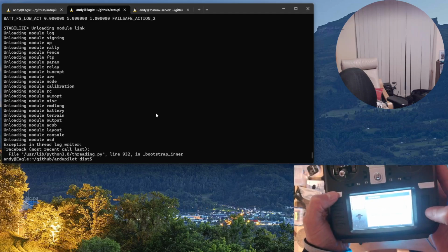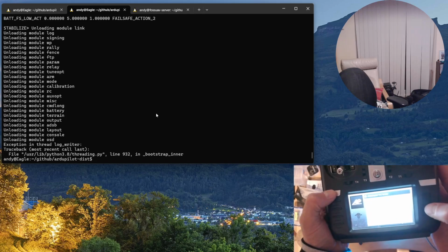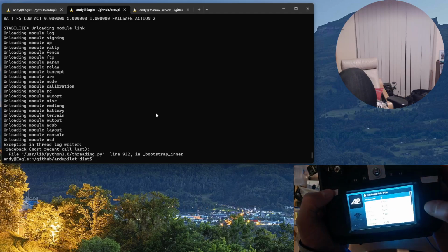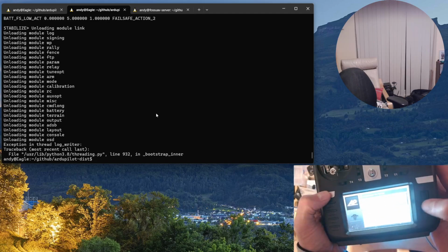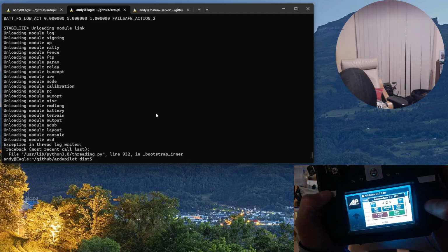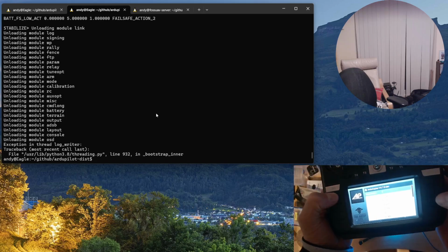And you'll see I've got ArduCopter there. And then you press ArduCopter, and hey, I've got Auto Tune Axis 2 on that menu, and then log disarmed as well. I can change that to 1. Perfect, parameter set.